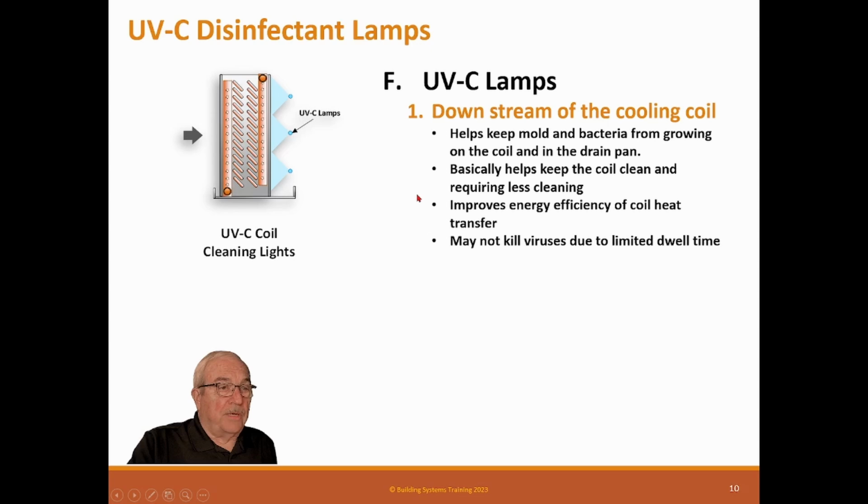Oh, there is only one other problem here. These are UVC lamps, and the C is basically telling you that it's a light that will kill bacteria. But remember, you're made up of bacteria, so they will hurt you. So the unit has to be installed so that if anyone opens an access door, these go off. You can't have these on. Number one, it'll blind you. Number two, it will actually give you a serious sunburn. So you don't want to be in a space and have those shining on you.